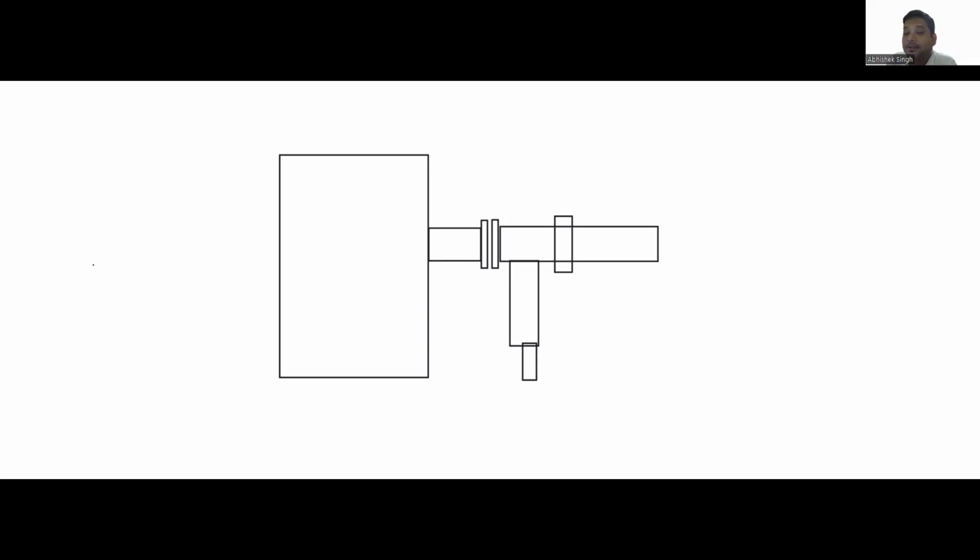If you are at the very start of a project, piping stress analysis is done at the very last, when all your piping configuration and piping layout are finalized, right? All the elevations and everything are fine. So at the last stage, they will be doing stress analysis. Exactly, this is what happened. And if you wait till that time to finalize your vessel, it will be too late to fabricate it, isn't it?